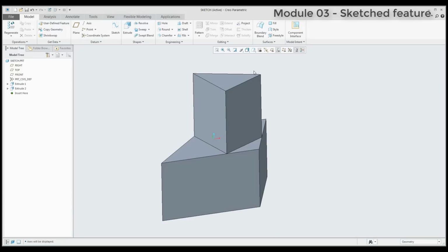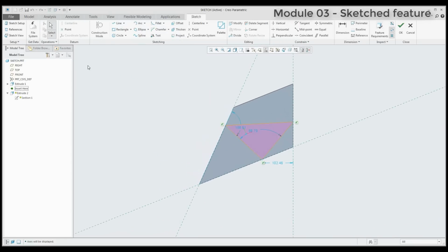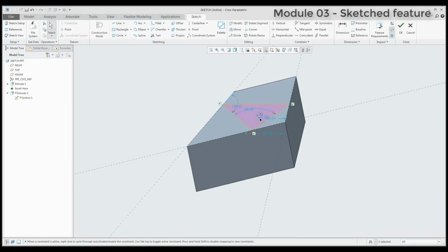Yeah, what is it good for? Because next time I'd like to use some hole on this axis. The best practice is to jump in the sketch, select the definition, and in the sketch, create a datum point. If you create a datum point in the sketch, for example here, the system will transform this point into an axis while the system creates the extrude feature.